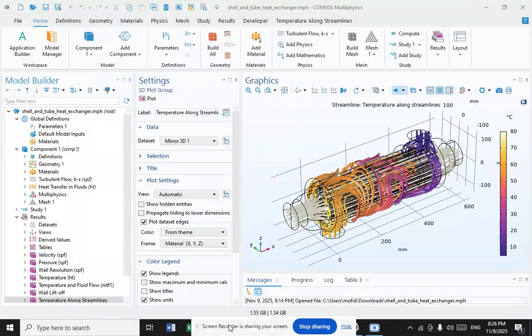A plate heat exchanger contains a number of thin-shaped heat transfer plates bundled together. The gasket arrangement of each pair of plates provides two separate channel systems. Each pair of plates forms a channel where the fluid can flow through. The pairs are attached by welding and bolting methods. The following shows the components in the heat exchanger in single channels. The configuration of the gasket enables flow-through, and thus this allows the main and secondary media in counter-current flow.